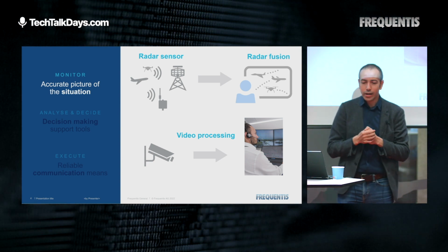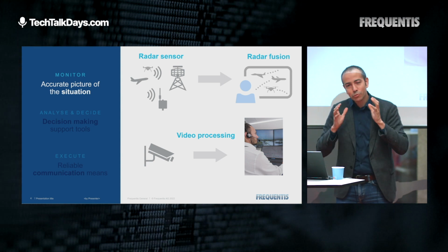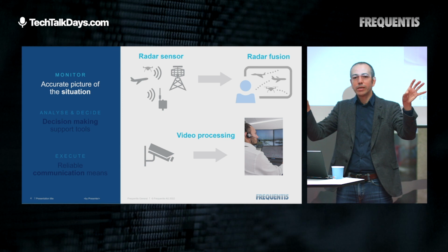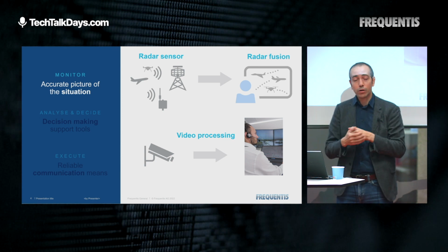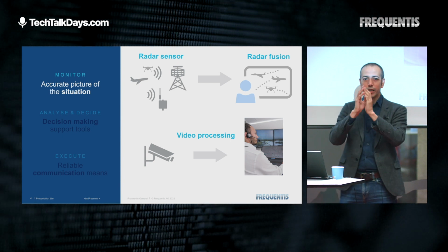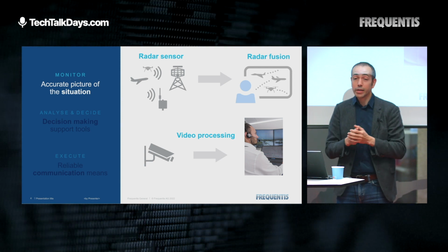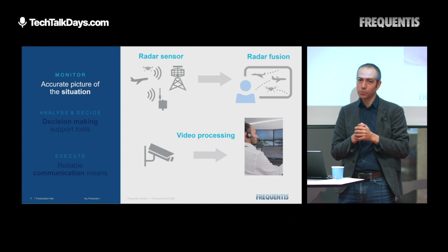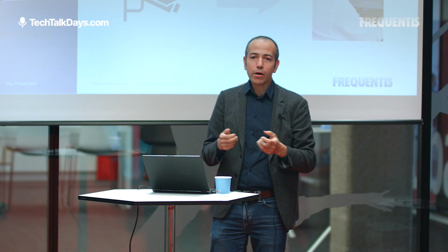And it's not only about surveillance information. We're also providing a video surveillance solution. That means we provide and install camera systems in airports. We process this information via complex video processing applications in order to provide the best picture to the controller, who can sit miles away. And that's what we call remote tower control. And it's not only about taking a video picture from cameras and displaying it at another location. It is also about processing this information. For instance, we rely on artificial intelligence algorithms to detect interesting information or remove undesired information from the video streams, in order to always provide the most useful information to the controller.